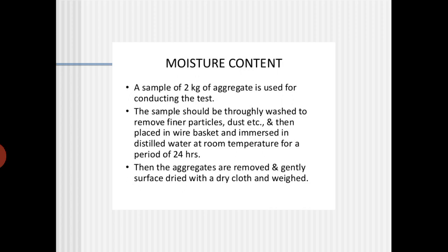Then when it comes to dissolved solids, these are dissolved in nature, which means you cannot see them. Colloidal and suspended solids you can see at least through your open eyes, but dissolved solids you cannot. You can only determine them by using a conductivity meter. If you use the conductivity of the sample, you will come to know how many total dissolved solids are there. Or you have to do it by one other method.